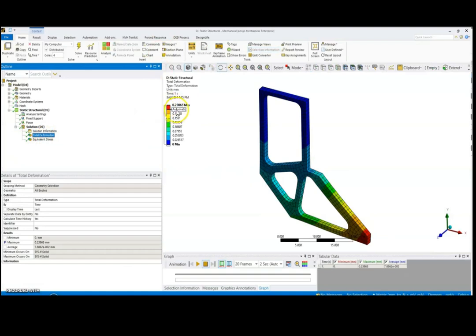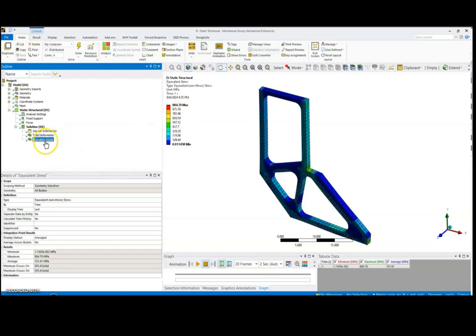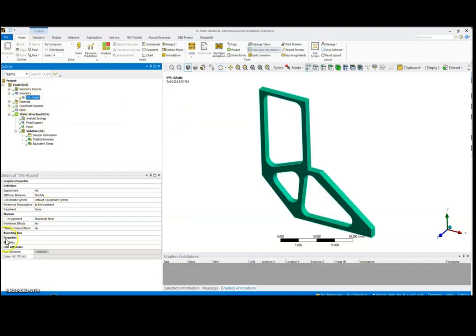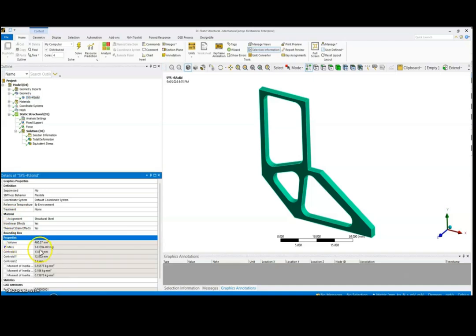The deformation is 0.238, which is slightly larger than just now, with the 2 mm thickness, which was 0.221. The stress also increased to 984, but it fulfills what we call the design constraint, which is less than 0.3 mm. At the same time, our mass, which is now the optimized one, is 0.0036 compared to just now with the 2 mm thickness, which was 0.004. So this is what we call the optimum design.